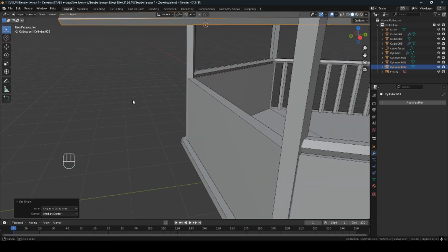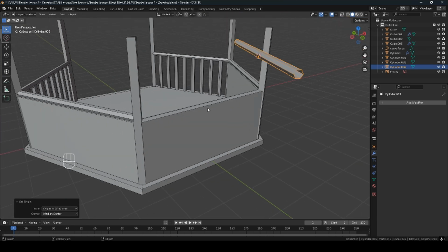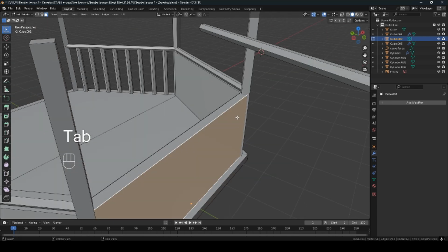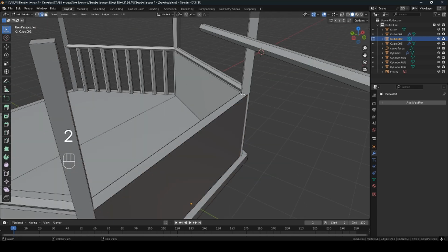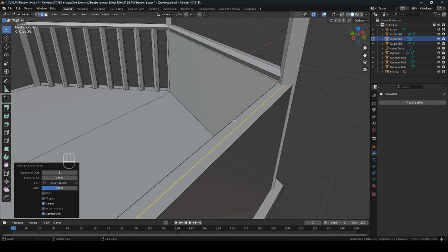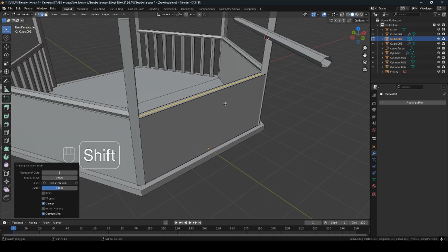To do that, there's again a couple of ways of doing that. We can just select the object for now, go into edit mode, press number 2 and just stick in a random edge loop up the top. What that does is it creates an edge loop going around. If you've seen my lesson 1, I'll talk a bit more about edge loops through that one.